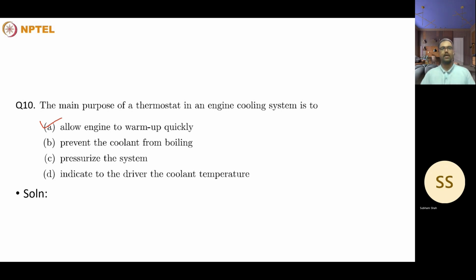In the previous question, the main purpose of a thermostat in an engine cooling system is allowing the engine to warm up quickly. So you got the right answer. And yes, sir, once the warm-up temperature is achieved, it will try to maintain that temperature for a while.